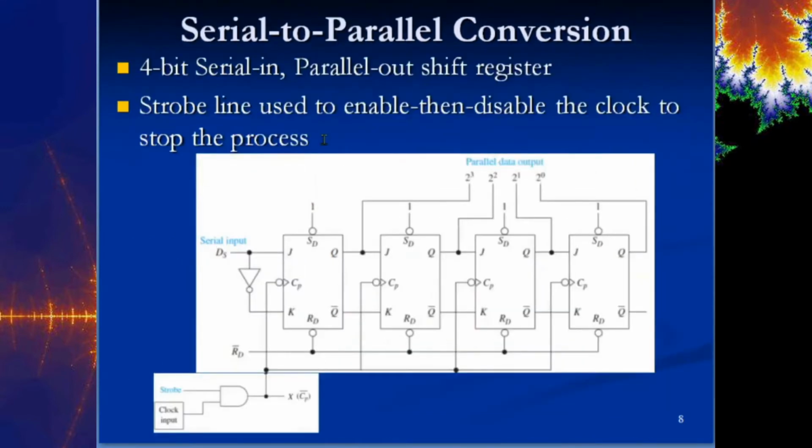All right, so here's serial to parallel. It's kind of going the other way. So you have the serial input load in, and then once the first data bit makes its way to the 4th flip-flop, then you can load that data out, okay?